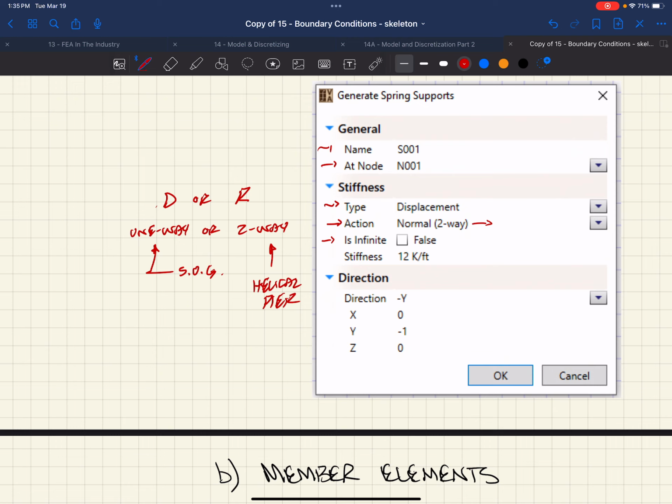And at that torque, there's an implied torque to tension or compression relationship. So basically the load bearing capacity of that helical pier in the axial direction is based on that applied torque. And they're really awesome. They work great. I've designed quite a few of them. Very easy to design. It comes out of table values. They're proprietary. So we as an engineer say, hey, I'm going to support axially in all these locations.